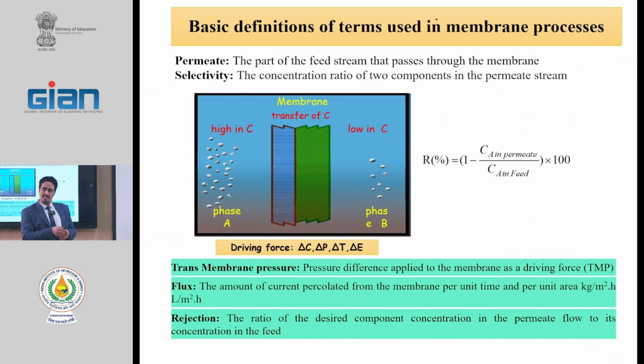In lab scale experiments, for example in your thesis, the measurement of this concentration is problematic. Maybe we need HPLC, GC, UV spectrophotometer, and other techniques for measuring, and accurate measuring is important. Analytical chemistry is important in this case. When we have a wrong analysis of concentration, our rejection will be wrong. Therefore, in lab scale, we need high technology for measuring concentration.